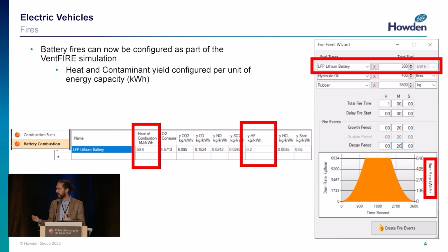There's another component to that, which is that from observation it's been observed that we actually get a lot more water going into the air from a diesel vehicle than the chemical equation for burning diesel suggests, and the thinking is that that's due to the wet environment that the vehicle is often operating in, churning up the road, that sort of thing. So a lot of water gets involved in that heat transfer process. And so something similar is going to happen for electric vehicles. Even though they give off sensible heat, there'll still be a lot of water involved.